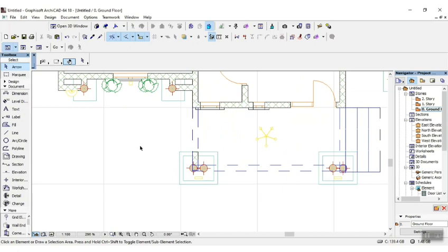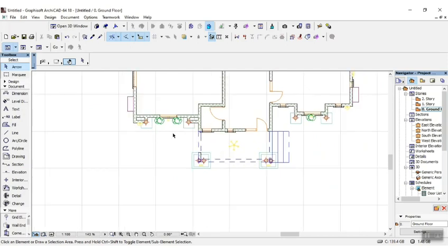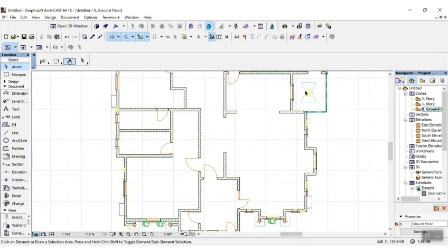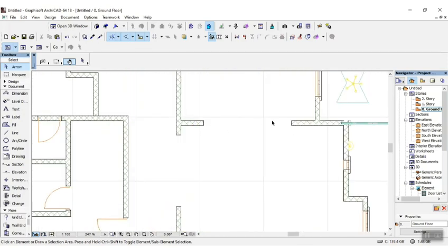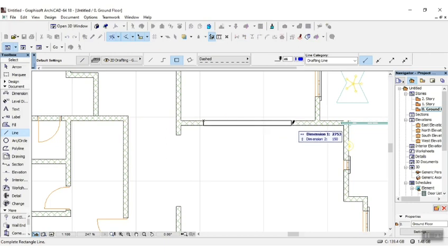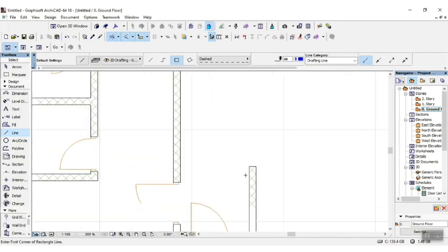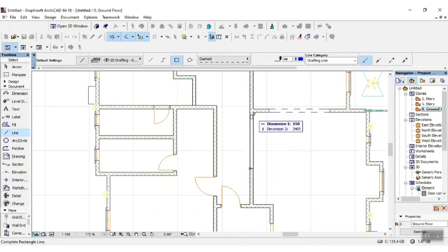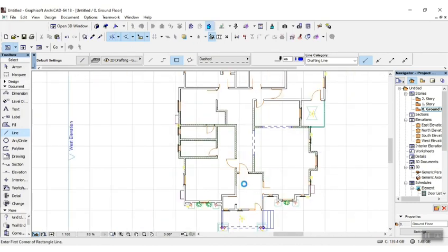You can either put the step from this side or from this side or from this side, or better still from all sides. But I'm just going to drop my own there. So I'll come down here. What do I need? This is the dining. I need to create a guide here, so they will know that there is a wall that ends at the DPC level. So you create a guide here. Okay. Then I'll create another guide here, because this is going to be for a sliding glass. This is the lobby. This from this ante room to this lobby to the main lodge.